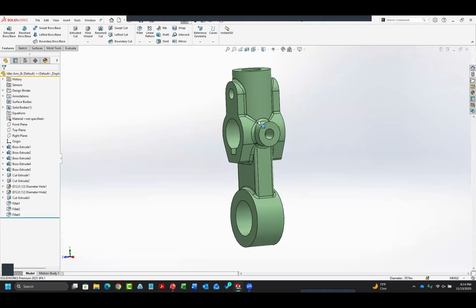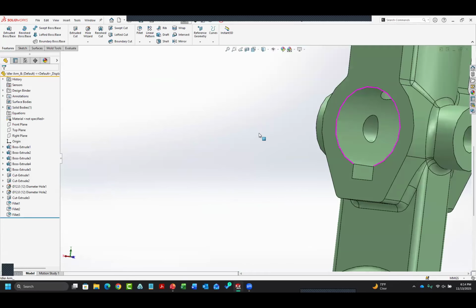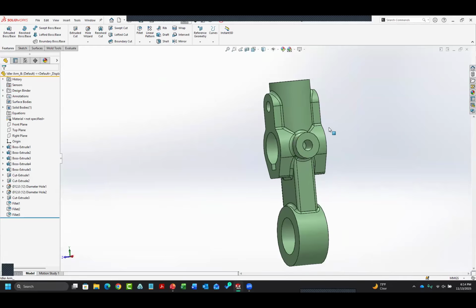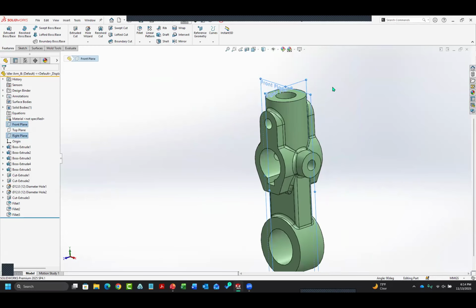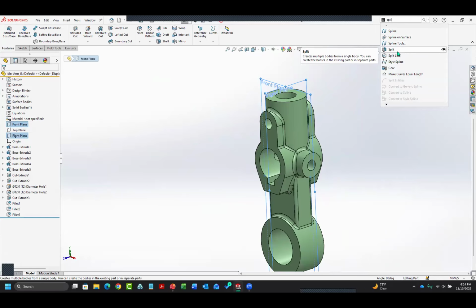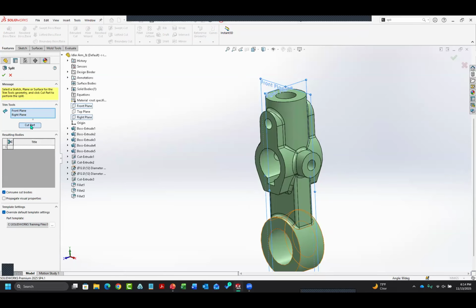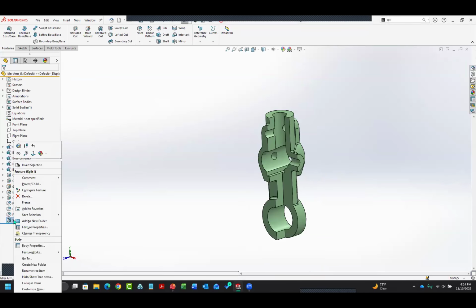So now if I look at this, this kind of grouping of fillets is in 4 places. I don't want to have to do this 4 times. When you start working with surfacing, definitely take a look at the type of symmetry that's in your model, because surfacing is like building something almost face by face. So you don't really want to have to do this a lot of times repeatedly. So I'm going to split this model into 4 sections, and I'm just going to keep the 1 section. I will eventually mirror it at the end.